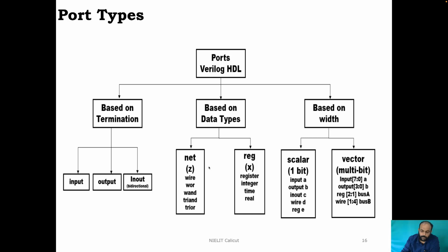So what I mean by default value is, you created a port of the type net, and before you start feeding it with any value, there exists a value in that connection, and that value is called the default value. And in the case of net data type it is Z, in the case of register data type it is X. Okay, for real it is 0 and so on.